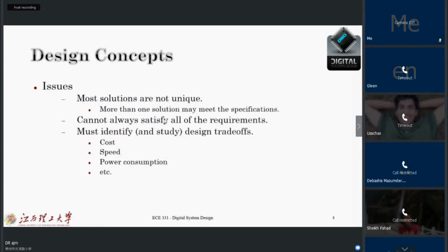And there is another part we should think about, which means that most solutions are not unique. You saw, for example, in the Karnaugh map solution, that if you select some loop, maybe your number of gates will be less, or maybe it becomes more. It depends on the skill and experience you have in selecting the loops, and also on the way you want to solve the problem.